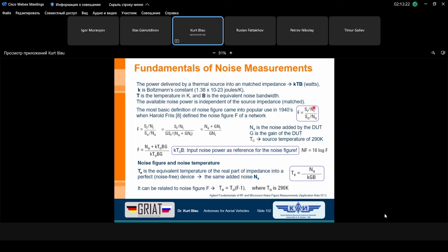But be careful with the noise power at the input. This noise power is the noise power which your receiver can only see at its input because of a lot of frequency-limiting elements, filters, the antenna, and so on. It's not a noise power which goes to infinity, as I mentioned before.